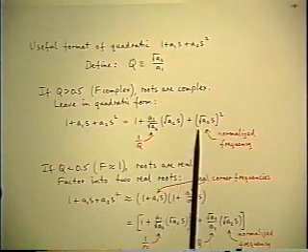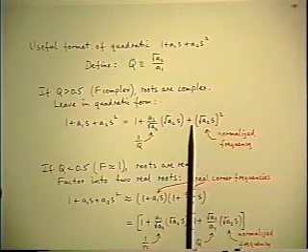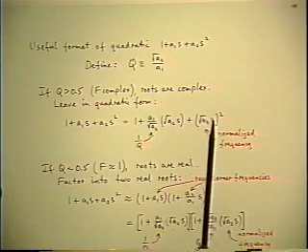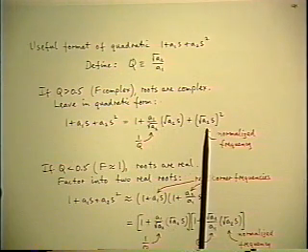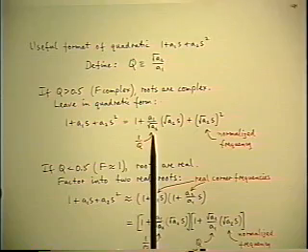which we haven't talked about yet, but we're going to shortly, to do with RLC filters. What you do is you define a normalizing frequency, and there's one parameter left, which is the Q factor.